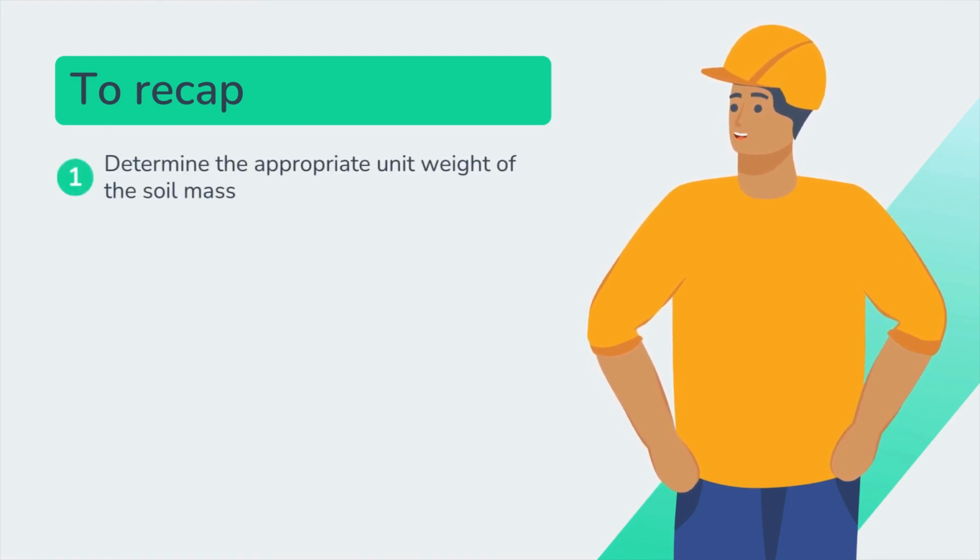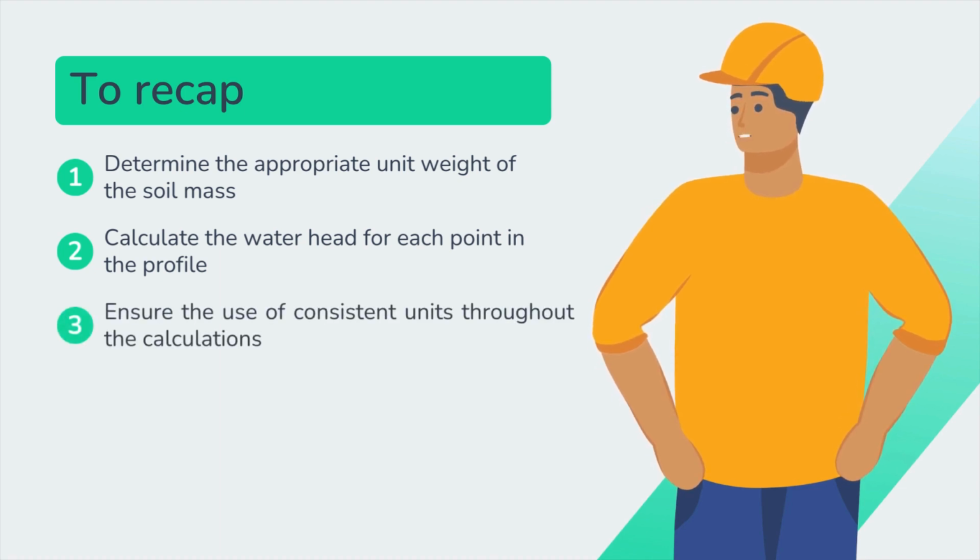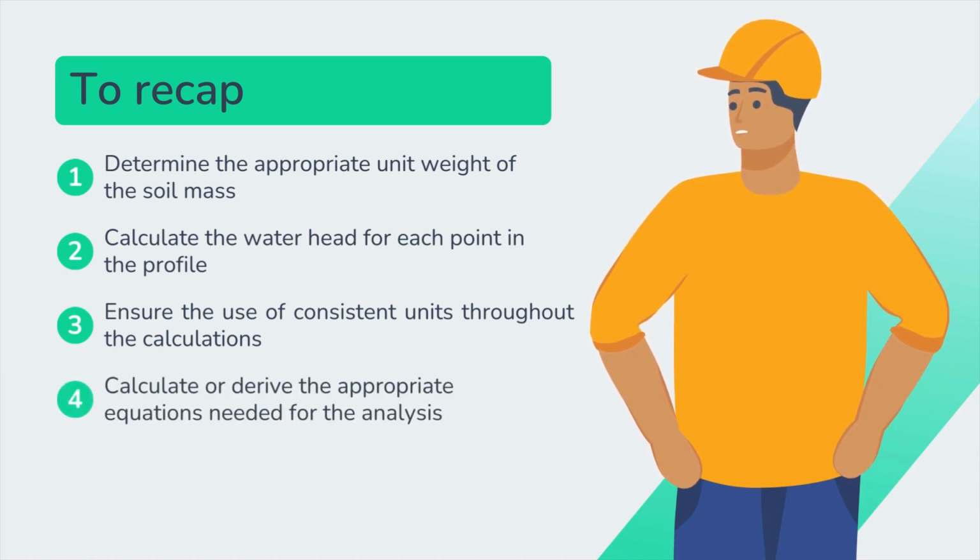1. Determine the appropriate unit weight of the soil mass. 2. Calculate the waterhead for each point in the profile. 3. Ensure the use of consistent units throughout the calculations. 4. Calculate or derive the appropriate equations needed for the analysis.